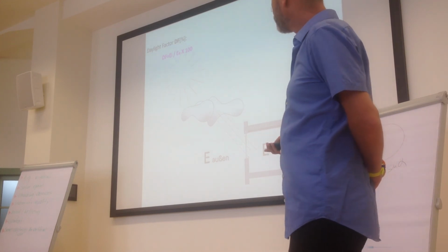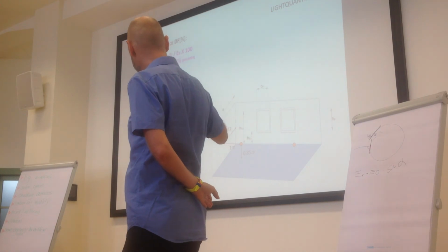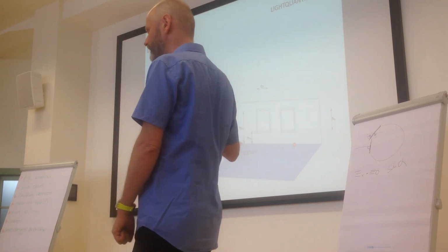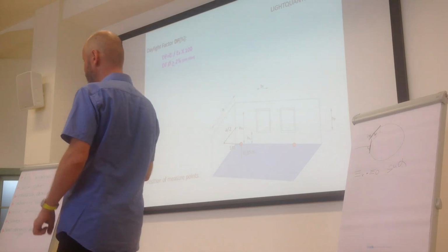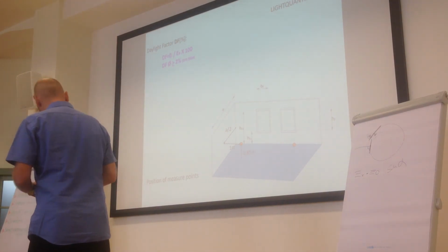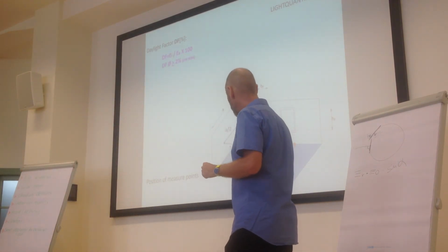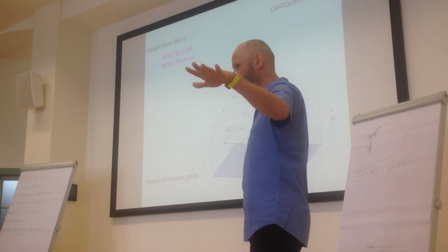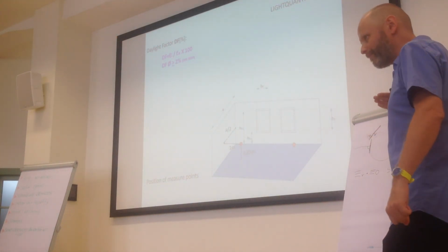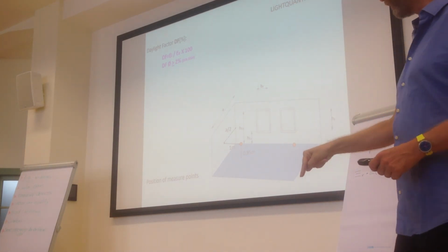And how can we now calculate, or how has this daylight factor to be calculated? If you do it according to the norm, without any computer simulation software, just by measuring, the daylight factor should not be measured near the window. It should also not be measured in the back of the room, not on the ceiling and not on the floor.